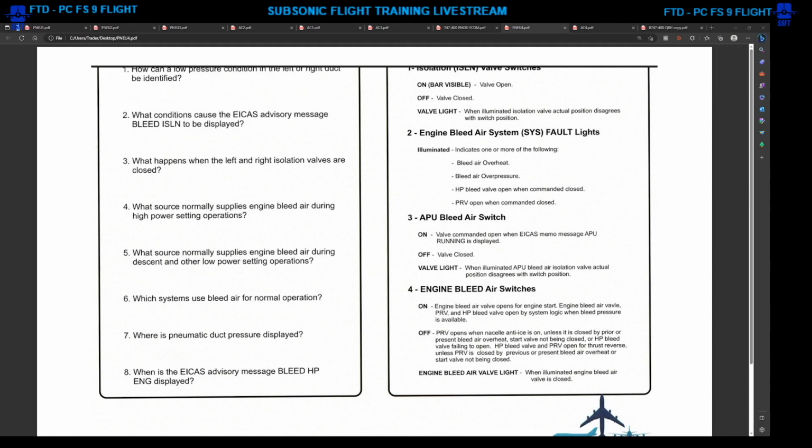This would be air conditioning, pressurization, wing and engine anti-ice. It's used for engine start. As we discussed, the leading edge flaps would use pneumatics. Aft cargo heat comes from the center bleed duct. Cargo smoke detection comes from the center bleed duct. Hydraulic reservoir pressurization to prevent foaming. The potable water tank pressurization is supplied by the center bleed duct. You have air-driven hydraulic demand pumps in systems 1 and 4, and the thrust reversers on the GE engines.